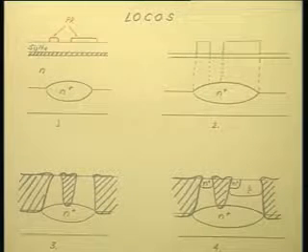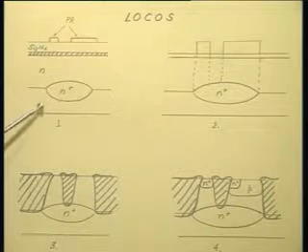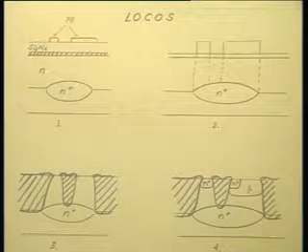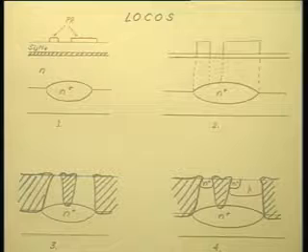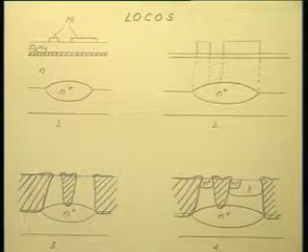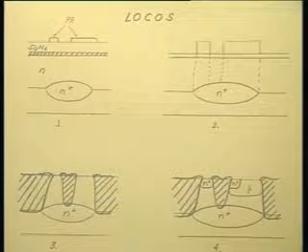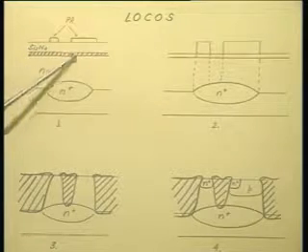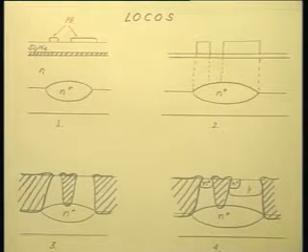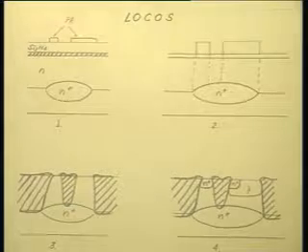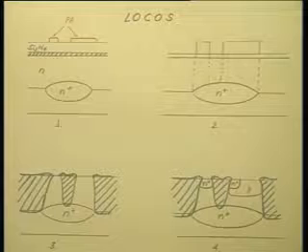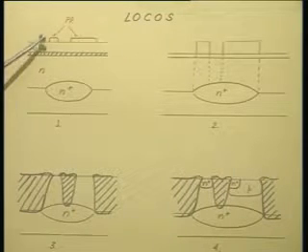Let us look at figure 1. What do I have? I have as before the p-type substrate, I have the n plus buried layer and then I have the n epitaxial layer. So far nothing has changed. So far my technology is exactly the same as the older day bipolar junction transistor. After this of course what have I done? I have a thin layer, this black hatched region, this is the thin layer of silicon dioxide which is called the pad oxide. On top of the pad oxide I have silicon nitride